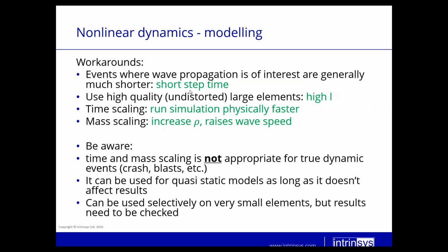which increases your stable time increment. Time scaling: you can run your simulation actually faster. That means, for example, if your forming process lasts for a second, you might be able to simulate it in 100 milliseconds or 10 milliseconds, provided you're not changing the result. We'll see a few slides in a minute where we discuss what the limitation on this is.